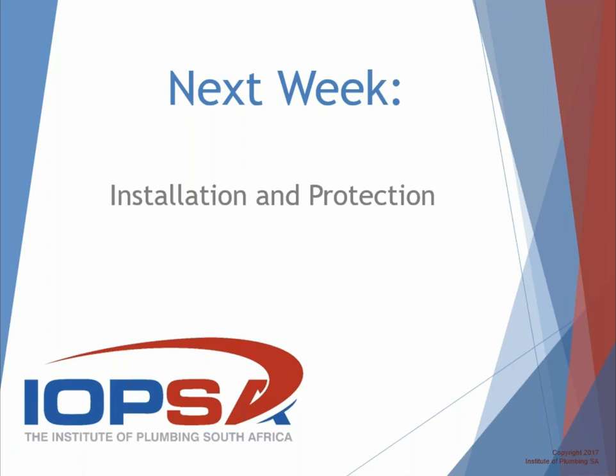I really am not. So I don't know whether it's an economic thing. I know that they use that expanded foam that you spray in for the steel tanks, and copper tank makers are also having to look at that technology, because the little polystyrene balls that they traditionally use between the copper and the outer tank will never result in a B-rated geyser. So that's a problem for them. So they're having to look at expanded foam as well. I don't know if it's inferior though.